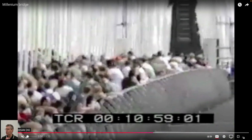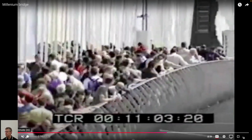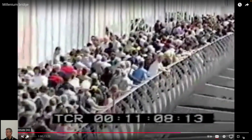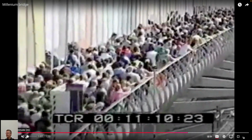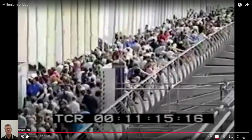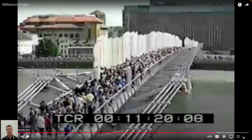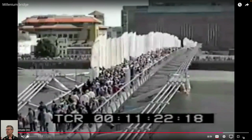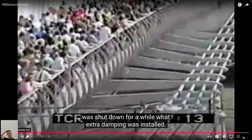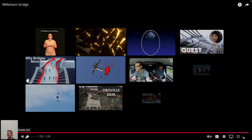And I guess they're talking in the text of this, there's a feedback. So the feedback is you walk across it, it starts to sway, and because it sways, you tend to start walking in step with that period if it's a comfortable period to walk in, and the people around you start walking at that same frequency as well. And as a result of that, it builds. So you see it's just not a wind loading in this particular case, but exactly the same feature is it's got some kind of input into it, which is resonant with the frequency of the bridge, and you can see people holding onto the handrail there because they can't stand up.